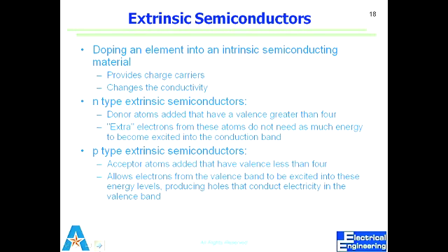Those atoms are rigidly stable in their position. It's just the holes or electrons that are traveling. So we have a very well-defined structure which results in degradation of the movement of charge because of collisions. So yes, we dope them, but there's something called mobility which falls off if we dope them too high. So we look at mobility also, but generally we dope them with two types of materials.